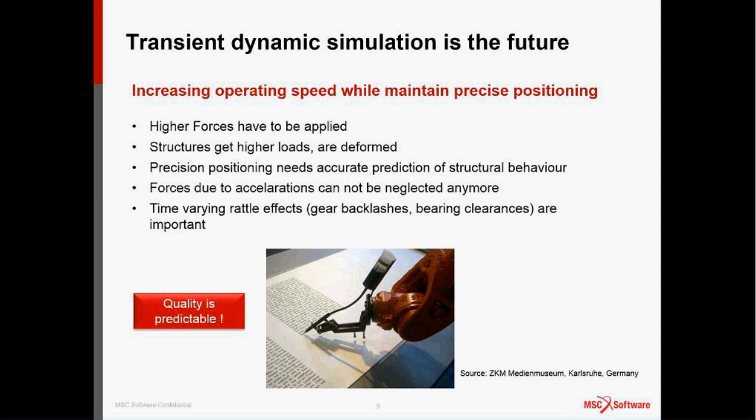So with the same amount of torque or force applied on a lighter object, you will basically be able to have a higher acceleration capability for your different robotic arms or other components of your system. So those are two different types of methods that can help you increase the speed of your robot.